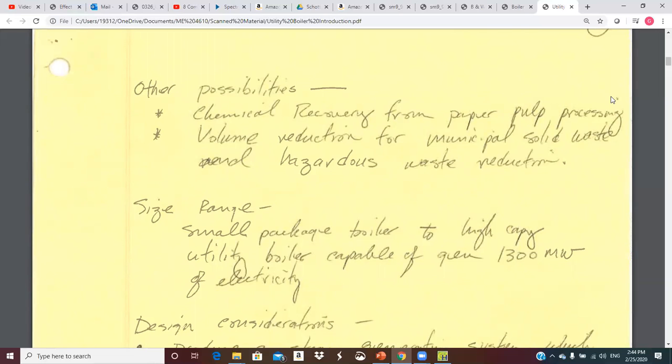They don't vent flash steam. If they have a high pressure condensate, they'll drop the pressure on it. Some of it will vaporize, and they'll take that vapor into a lower pressure header and use it. And they keep flashing the steam as the condensate pressure comes down. They're very efficient. A good paper mill is really an incredible place for a thermal science person to work.